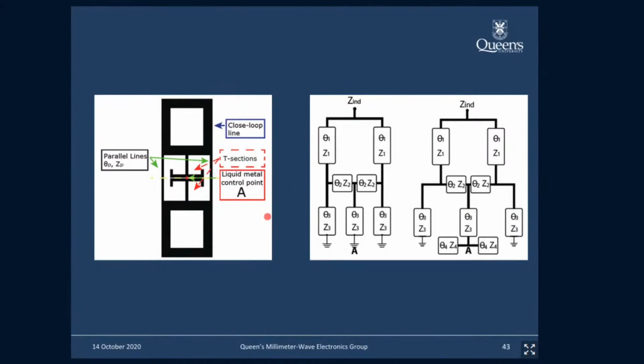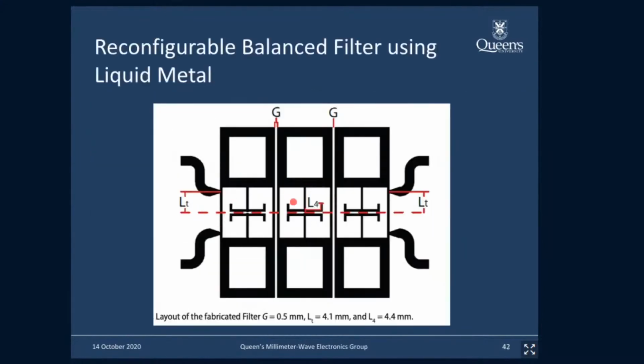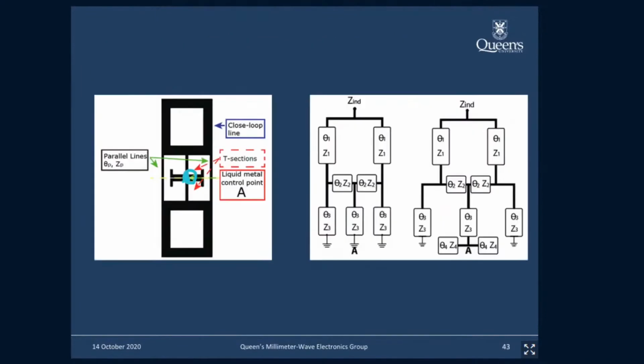So this is just one pair of resonators, right? So top and bottom. And if you add a droplet, I'm going to change the color here to something a little bit more distinctive, perhaps. If you put a droplet of liquid metal here, then you essentially create a physical short there. I mean, there is a virtual ground there anyway, because it's a symmetric structure, so you will have a virtual ground. But here, if you put a liquid metal drop here, you actually, of course, create that short there. And so that'll tune the frequency of this ring.